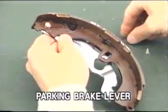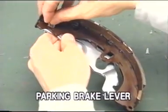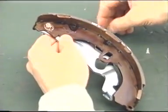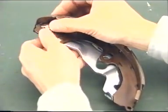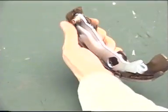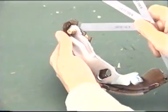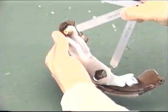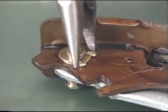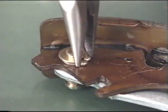Install the parking brake lever temporarily to the rear shoe using a new C washer. Measure the clearance between the brake shoe and the lever using a feeler gauge. Replace the shim if not within specification. Assemble the C washer using a pair of pliers.